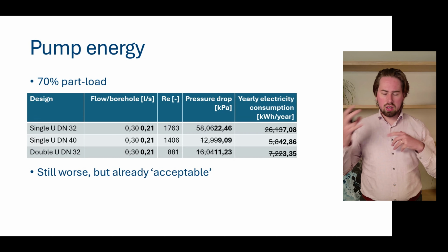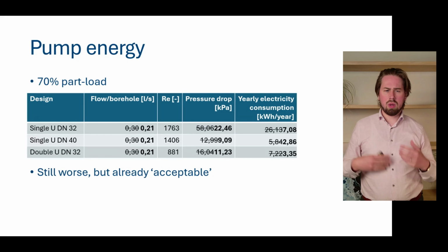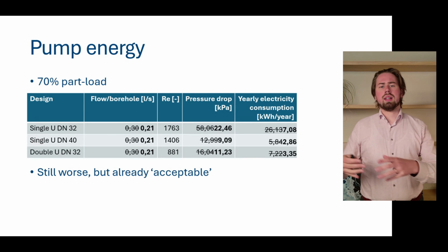So when talking about these pressure drops and saying, well, the single U has the highest pressure drop, that's true. But if you look at it from a pump energy consumption point of view, where we have different flow rates, the difference is actually not that pronounced or significant, I would say. So that's a little bit of nuance.